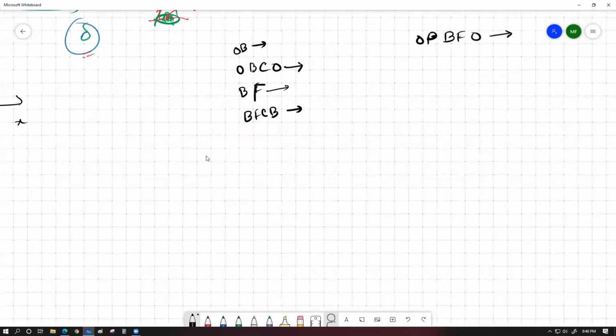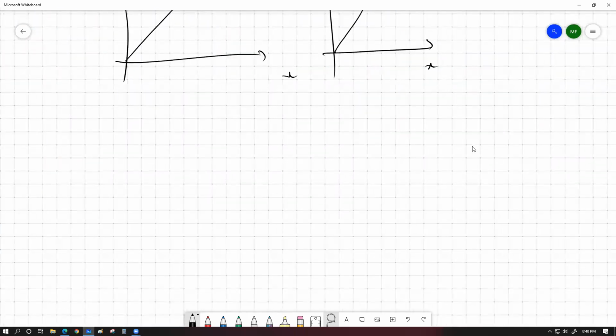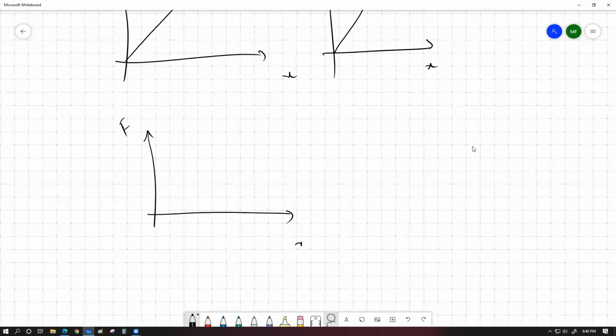Thank you, sir. What happens to the polymeric substances? Polymeric substances behave like this. This is the typical stress strain graph or force extension graph of a polymeric substance. While loading, polymeric substances have no straight line portion within their curve whatsoever. So while loading, they follow a graph that somewhat looks like this. So let's say this is loading.